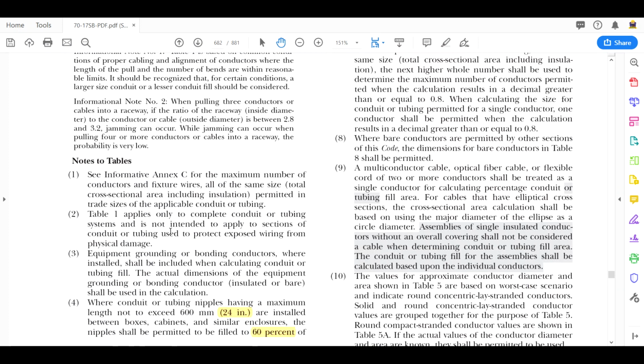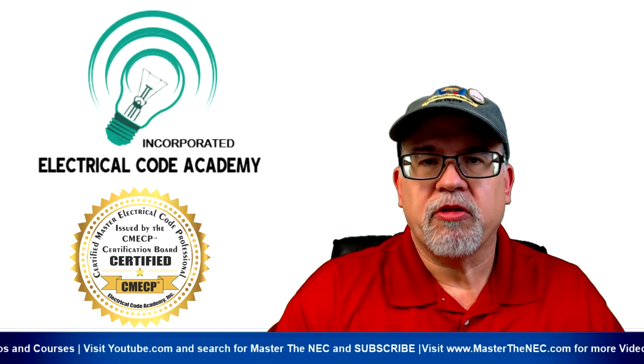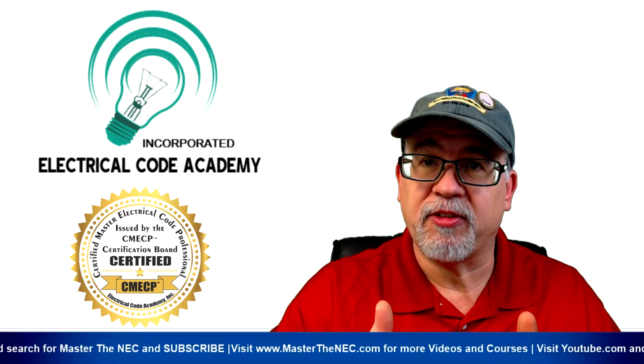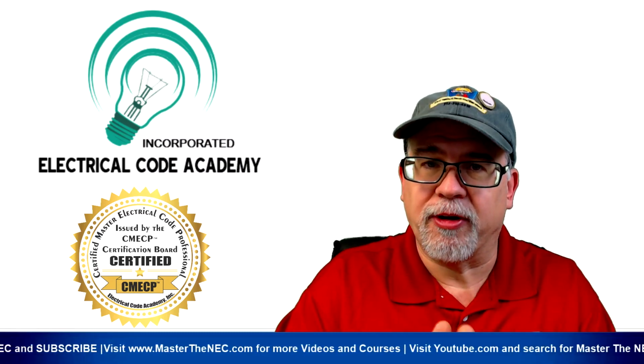All right, now what about these little notes? Note number 1 says, if I'm installing conductors in a raceway and I'm using all the same size conductors, and I'm worried about not exceeding the 40%, then I can go to Informative Annex C, and that'll tell me the maximum number of conductors or fixture wires that I can install inside that raceway. I'll give you an example. If I have an EMT, electrical metallic tubing, trade size 1, and I want to know how many THHNs I can put in there, I could go to Informative Annex C because they're all the same size. They're 14 gauge. If I go there, it'll say that I can put 35 in there.